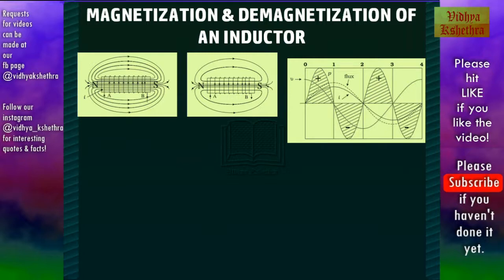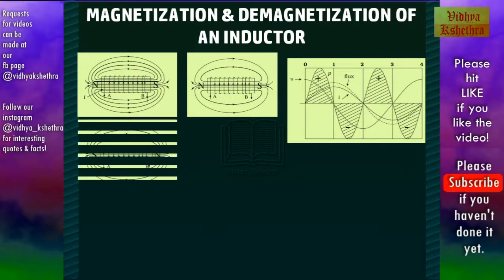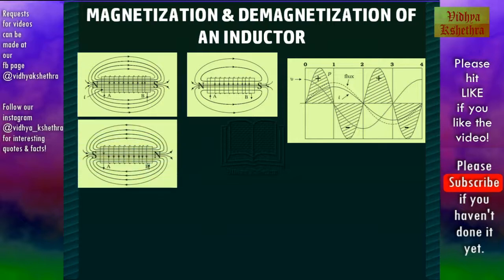Since the sign of voltage is negative and that of current is positive, the resultant power is negative. Hence, energy is given to the source from the inductor. Now, from 2 to 3.